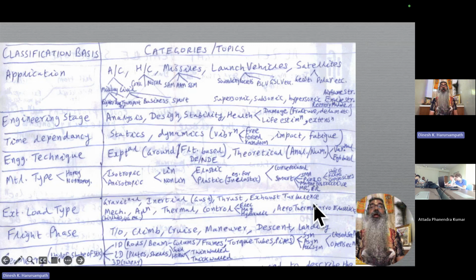In a shape memory alloy, there are changes in the internal structure of the material based on the temperature. An example of a shape memory alloy is nitinol, made out of nickel and titanium. That is something which will have two different phases, called austenite and martensite. Then you will have different internal crystalline structures, and based on that, the properties will vary. So those can be taken advantage of.